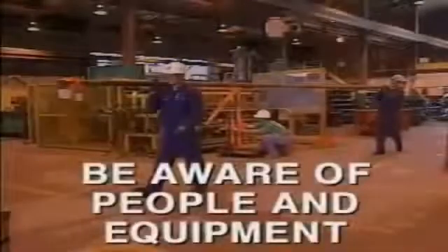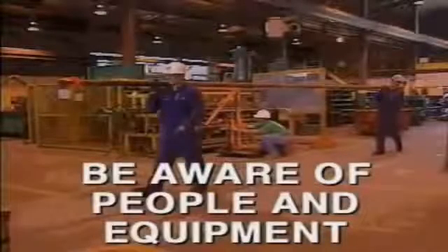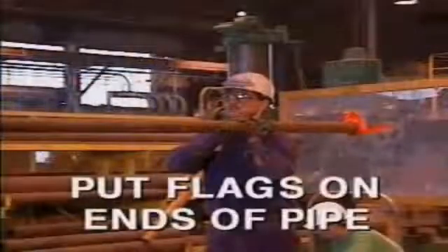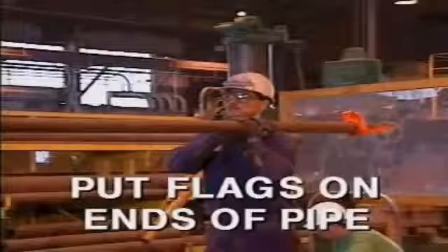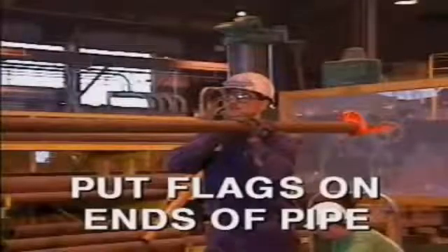Be aware of the people and equipment around you when you're handling or transporting pipes. Put flags on the ends of long lengths of pipe so that you and others can easily see the ends and avoid damage or injury.